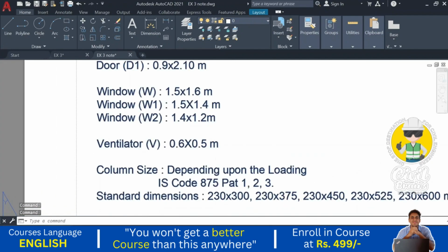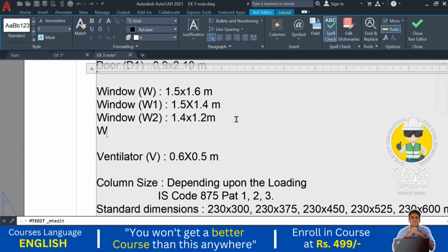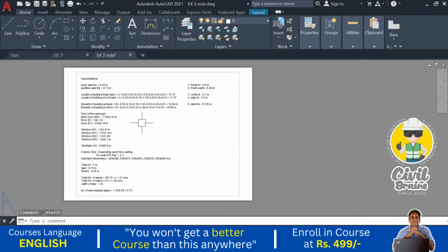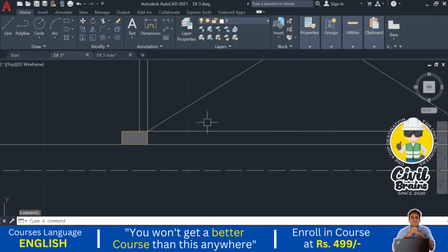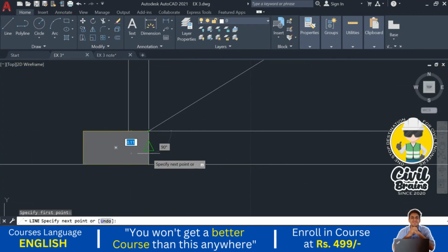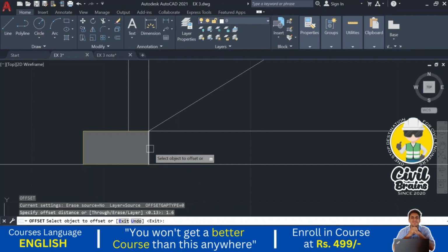We can consider another size, that is window W3, a huge window we have provided over here. This size is 1.6 by 2.1 meter. Okay, so we just show it in the plan and in the elevation also. From this corner that we have provided in the plan, I just use the offset command 1.6.